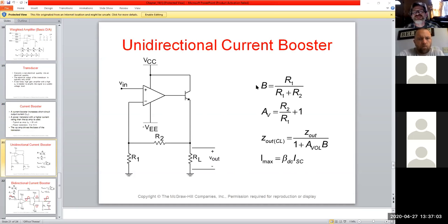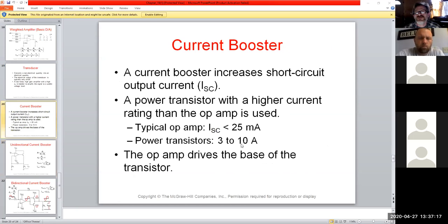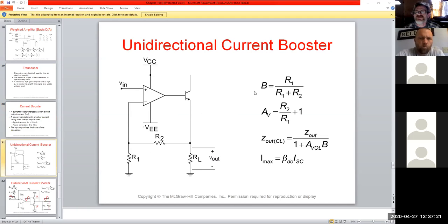It might be interesting to take a look at this because of the combination of the transistor and the op amp together. These are widely used for any kind of driver circuits. You would run into this combination where you want a high current output. You very typically would have this circuit. We might take a look at it as a little review, have you guys juggle a couple of values and compare it to what you get on the simulator.